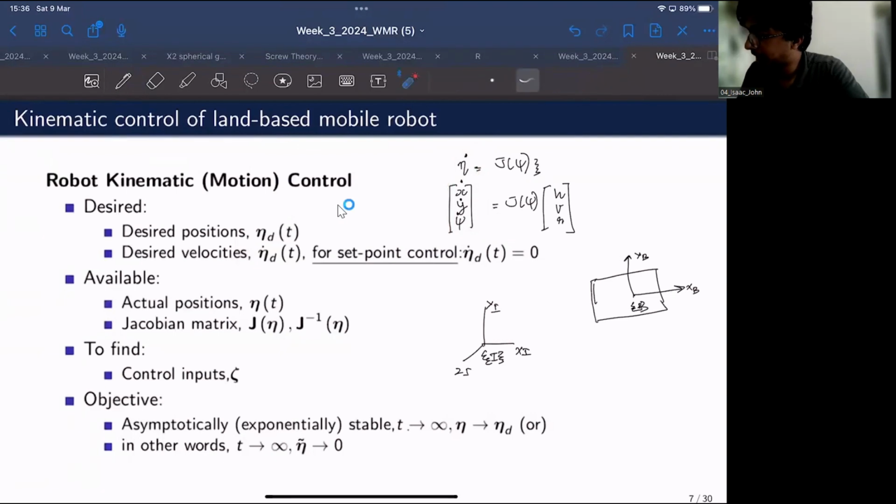For the trajectory of the centroid of the body frame, it's intuitive for a human being to define it with respect to the inertial frame of reference, because the observer will be based on the inertial frame, and it is easier to observe the robot's motion defined with respect to it. So most often we would specify the desired trajectory in terms of task space coordinates, or inertial frame coordinates.